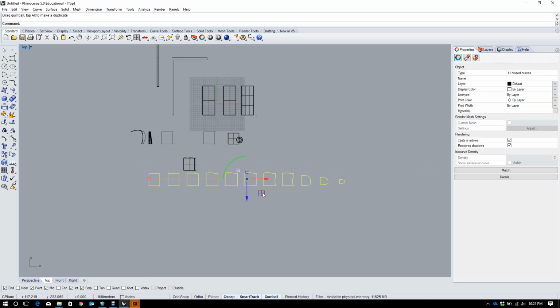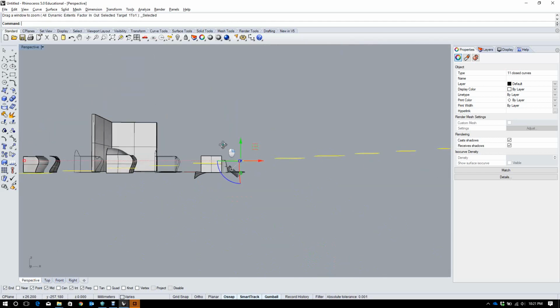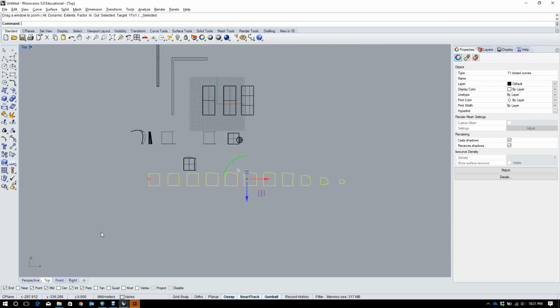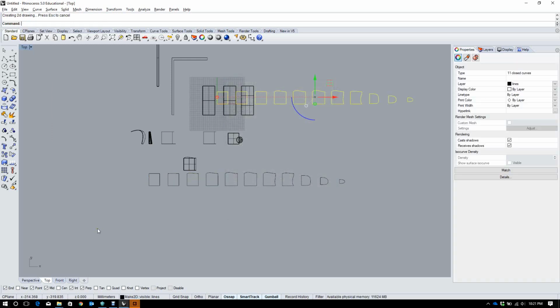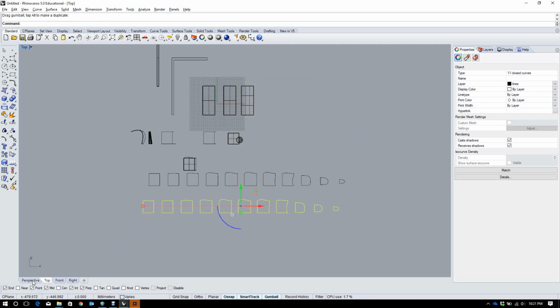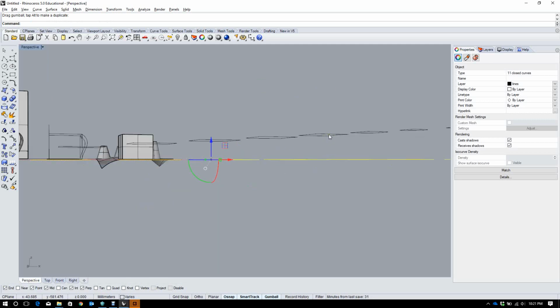The other thing I think I may have missed out is that when you actually use share, it separates the line work, but it doesn't put it on the same plane. So again, an easy fix for that, just make 2D, and now all of them are flat. If you go to perspective, you see that all of these are flat and the original one isn't flat.